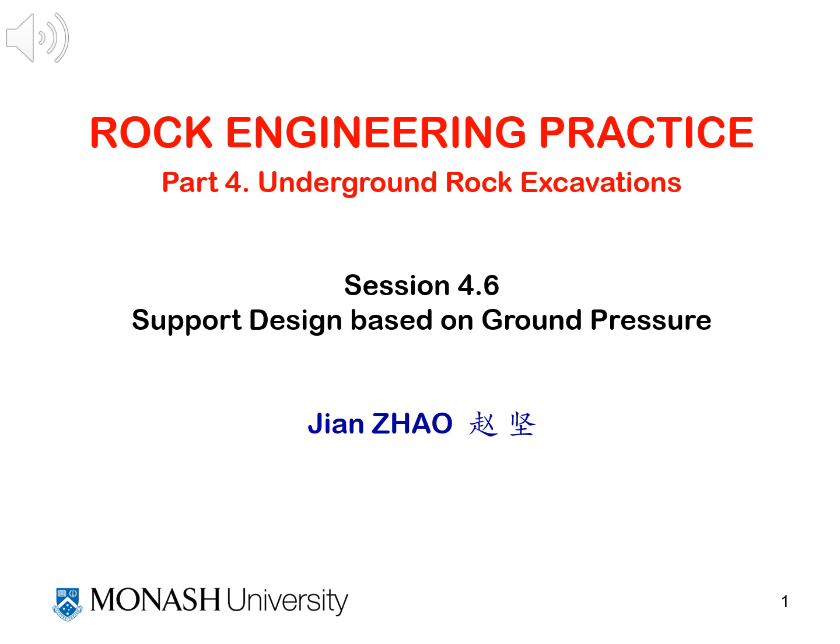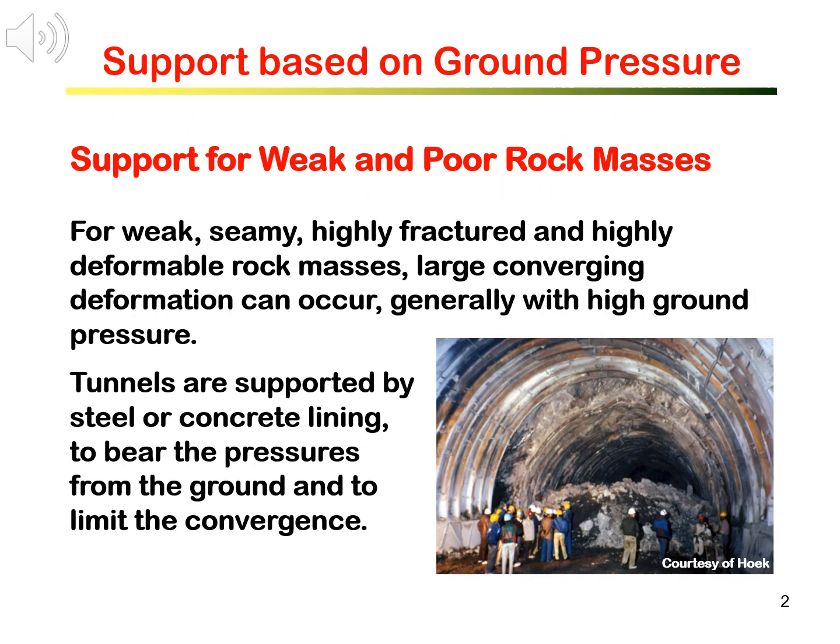Hello and welcome back. We have learned in the previous two sessions on rock support design using rock mass classification systems. In this session, we will go through support design based on ground characteristics, particularly on ground pressure and ground deformation. Rock support using rock mass classifications is considered traditional hard rock design.